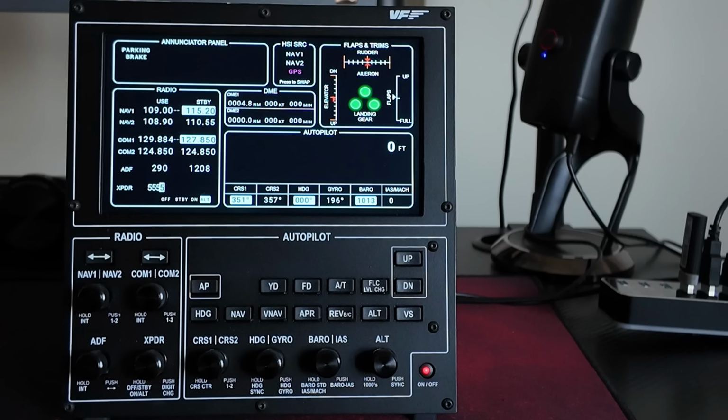Top left, it has an annunciator panel. Here you can see the parking brake on. You'll also get notice if pitot heat's not on, as well as a wide variety of system malfunctions. Next to that, you have the HSI mode indicator. What's really nice here is you just touch it here to change from GPS, Nav1, Nav2 and so on. And next to that you have a flap and trims indicator, which also shows the status of your landing gear, green for down, red for transition and off for up.